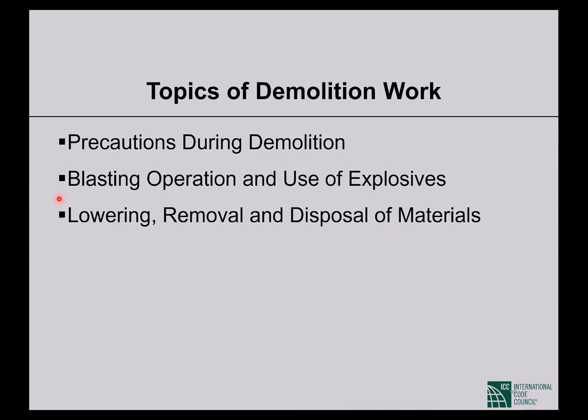And because of that, and the Ranks building was a flat slab building, the flat slab collapsed by punching shear. And you know, once a punching shear happens, subsequently all other points actually collapse, and the entire floor collapsed on top of another floor.